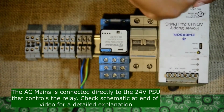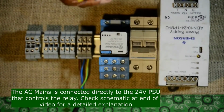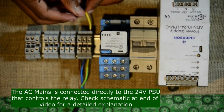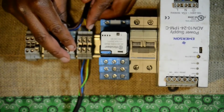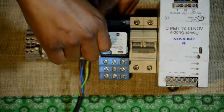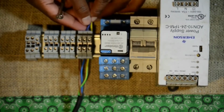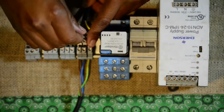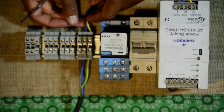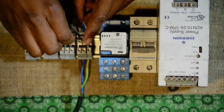So what's gonna happen is that our power from the mains is actually gonna power this 24 volt DC power supply, which in turn is gonna close our relay contacts. So we take these ones directly to the 230 volts connection that we just made.